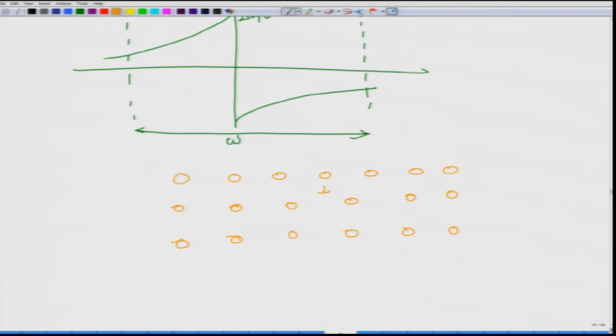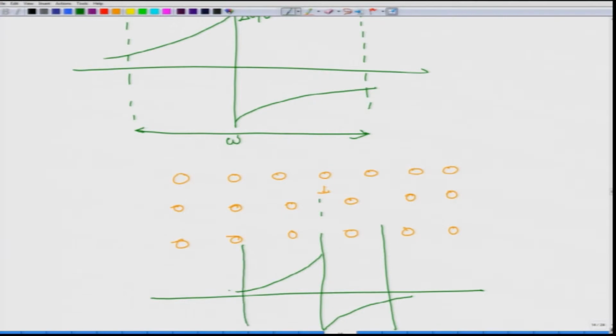Over here, but if you see the lines over here, they have already acquired the original shape. So, there is no more strain at these positions, and if you now draw the strain values, what you have is something like this. So, this time the 10% strain, which is where the linear elasticity does not hold, is limited to a much smaller region. Let us call it W1, and let us call this W2.